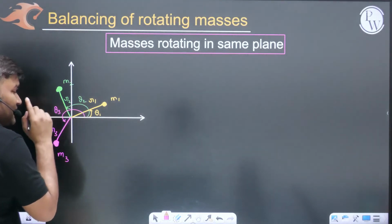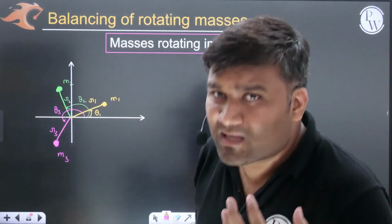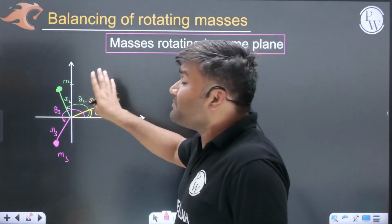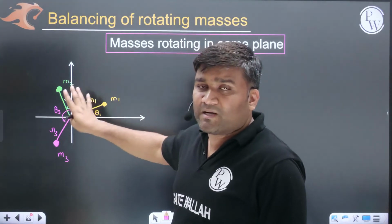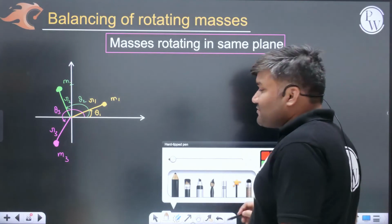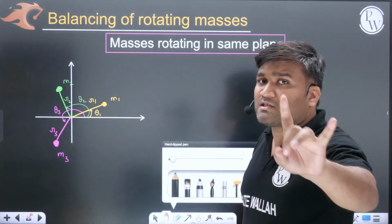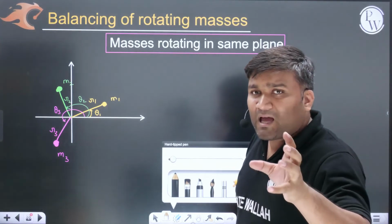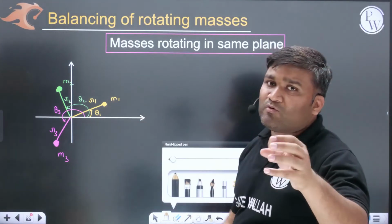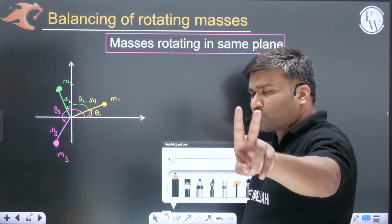This is the θ3 angle. First of all, you have to check whether this system is completely balanced or not. If this system is completely balanced, I can very easily say the summation of all these forces will be 0. If the summation of forces is not 0, then I have to add one balancing mass in the same plane. In examinations, two kinds of questions can be asked.